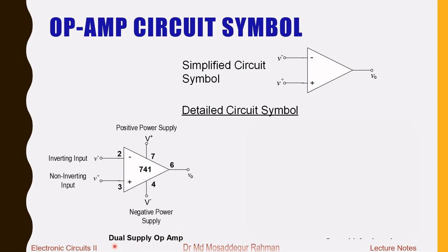Say, dual power supply, why are you calling it dual power supply? An op-amp by its nature has two power supplies, so why call it dual? This is because you can also have an op-amp with a single power supply. It's not necessary to have two power supplies all the time. Sometimes there are situations where you do not need the negative voltage. You don't have to apply the negative power supply, you just apply the positive power supply.